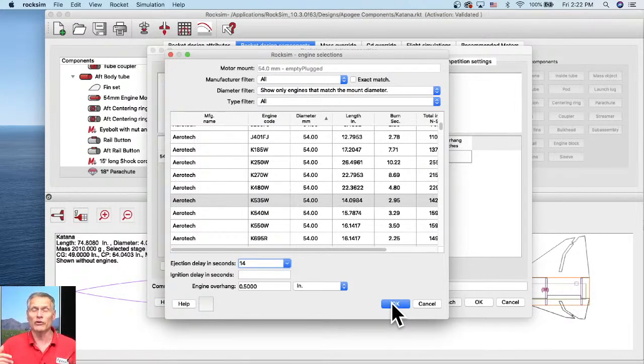And so you're gauging your own skills in packing a parachute. And so for your first launch, you better be conservative. So assume that it's going to take a long time to unfurl and then completely blossom open. And during that time, it's going to fall pretty far. So if you deploy it too low, it might be on the ground before it finally opens. And then that kind of defeats the purpose of dual deployment too, because now you're going to break fins off your rocket.